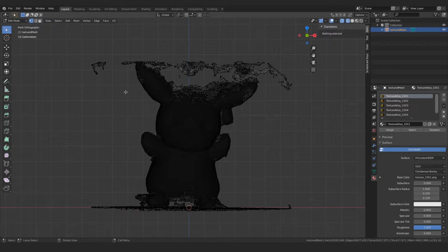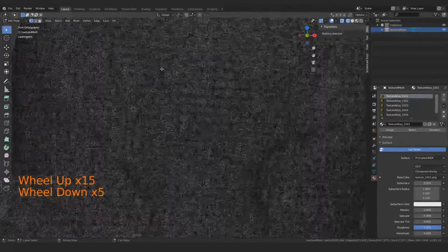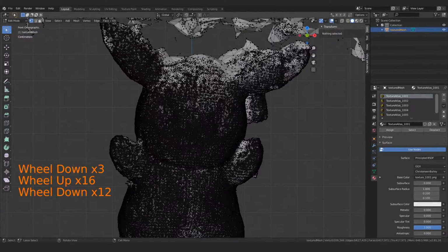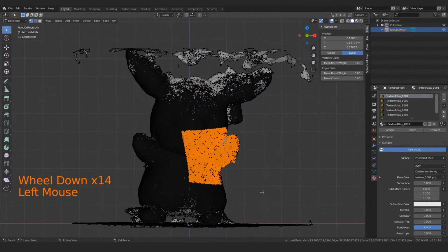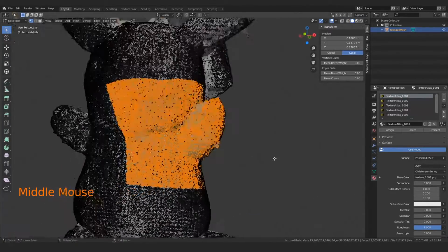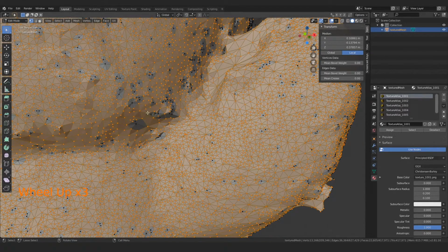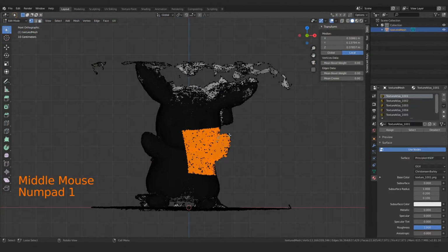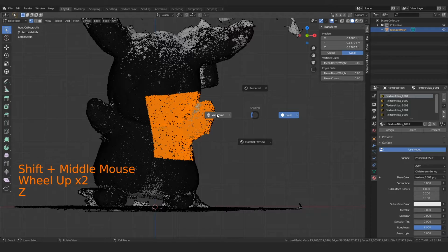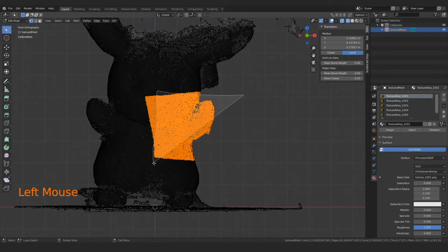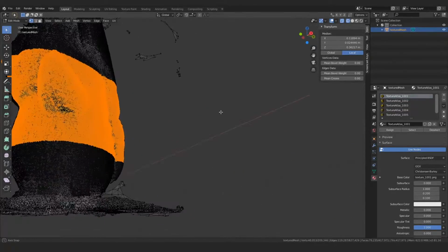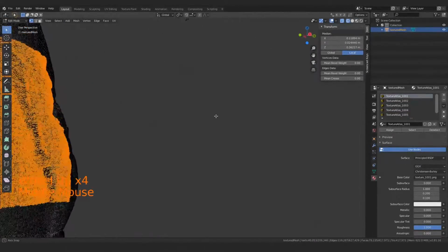Now the reason I had us go into wireframe mode before I entered this view was because I can see through the model. So if I switch this to solid, I can no longer see through the model. I can only see the front side. And so if I try to select a big selection here, you'll see I didn't get all of those points. In fact, some of them were even obscured from the front view that I didn't get those. And I certainly didn't select through the model. Now if I switch this back to the front view and I switch to a wireframe mode and I draw that selection again, you'll see now I've gotten everything that was in the view because I can see through my 3D model, which is exactly what I want.